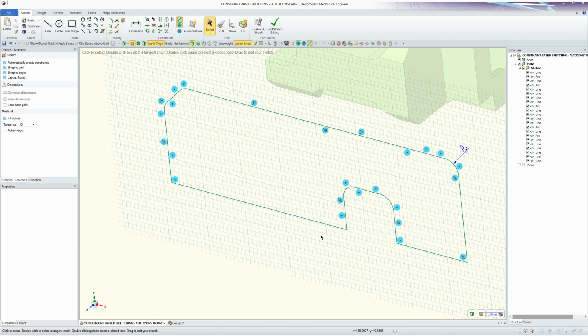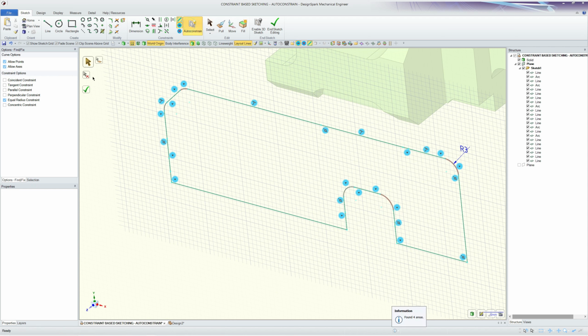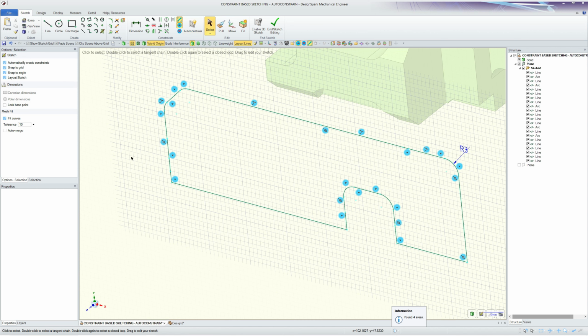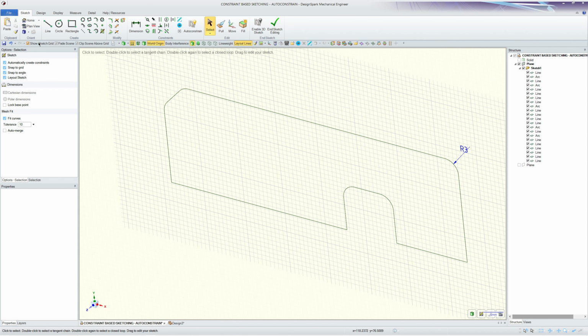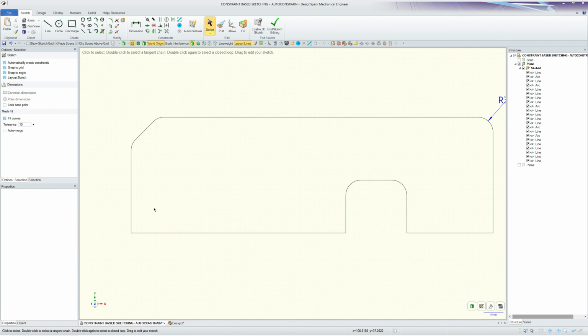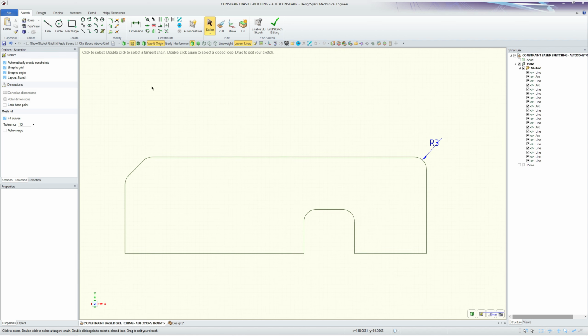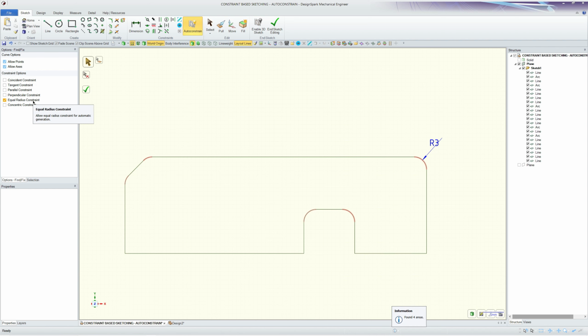Before moving on, I want to add that with auto constrain, there's also the ability to exclude areas from searching. Let me first clean up the display so it's clear. Let me turn off the line color, off constraint tips, off grid, and I'll now view. Okay, now let's go into auto constrain.